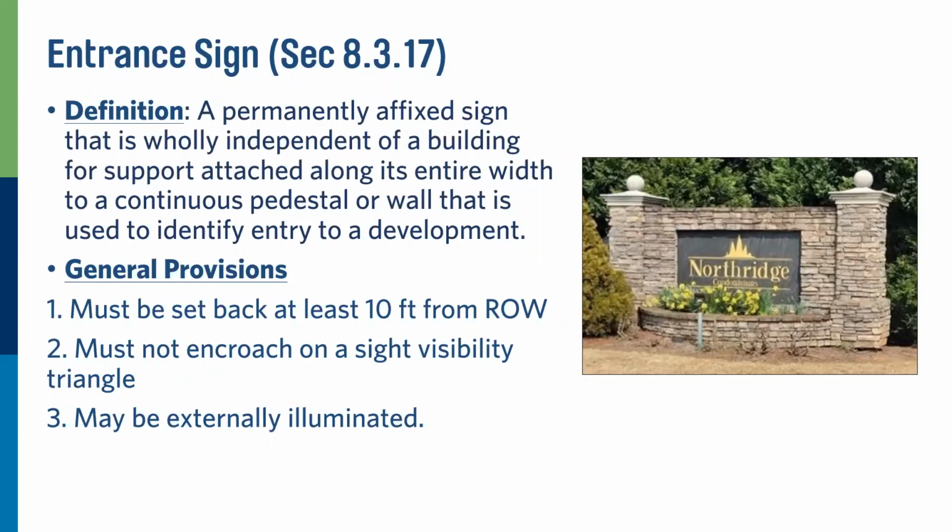Say if you have a 50-foot right of way, your road might be 25 feet wide. That's 12.5 feet split each way on the road, and the difference is the right of way. So in essence, it's outside where your utilities are; the power pole, the sidewalks, all of that is in the right of way. So you can't put your sign anywhere where that infrastructure is in place. You have to be outside of that.